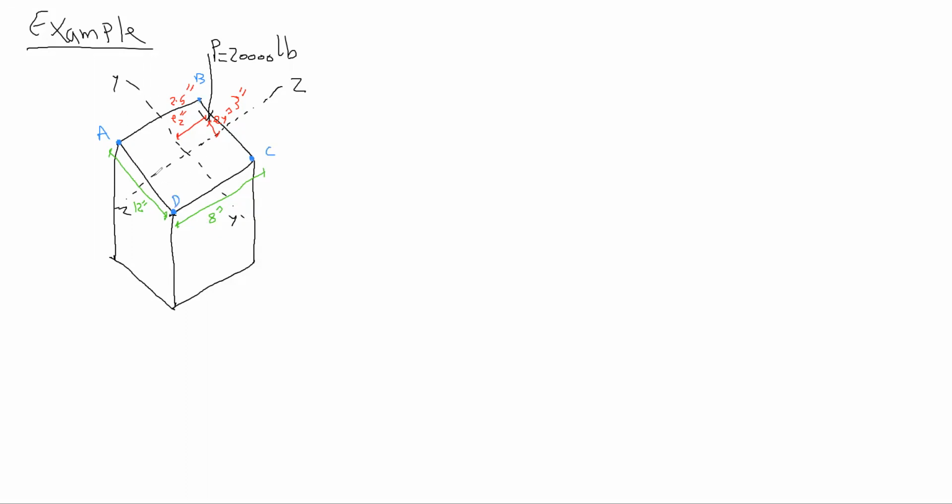In the previous problem, last lecture, the shape was a T-shape. There were lots of calculations. We had to find the center and the moment of inertia. But here it's just rectangular, which means the center is just in the middle, right? So in this situation, EY makes a moment in one direction, and EZ makes a moment in the other direction.